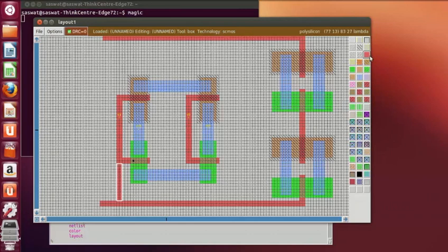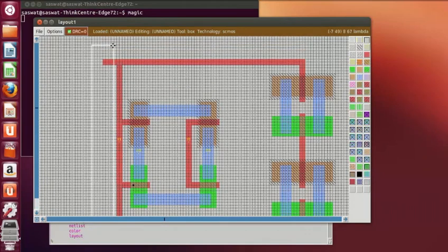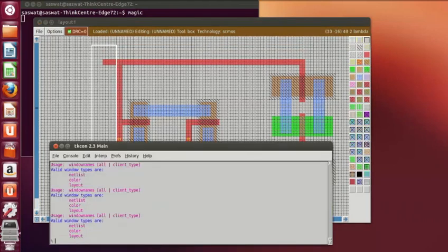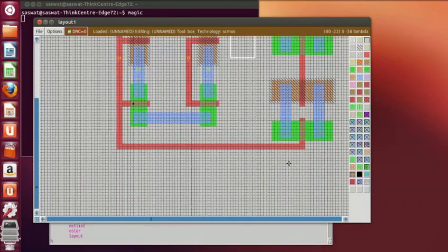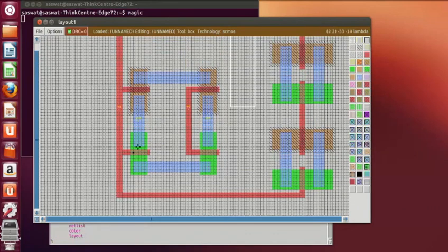And then middle click on M1, middle click on poly, directly this can be drawn, then from here to here erase. Okay, now this is VA, A connected. Now A bar, this A bar is connected over here,